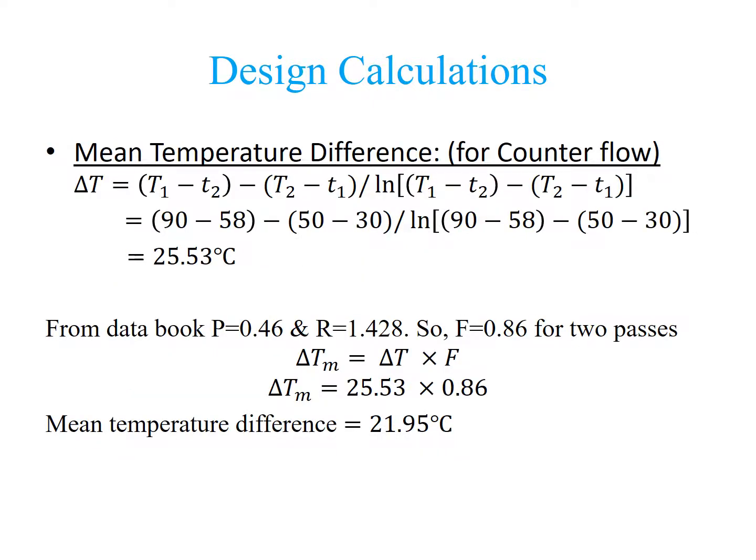Mean temperature difference. Since we have decided to calculate for counterflow, what is meant by counterflow? In the shell, the water will be flowing in one direction, and inside the tube, the oil will be flowing in the opposite direction. This is called counterflow.